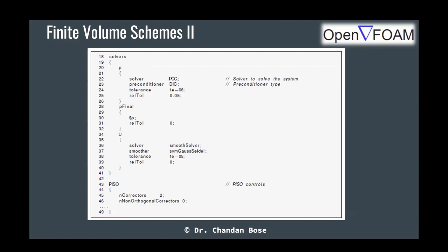There can be two reasons. One is that you have given a wrong name. The second is that you have not activated the OpenFOAM environment. In that case, even if you give the correct name, it will not be able to find it. So you have to source the bashrc file. If you forget to do that, it won't recognize that OpenFOAM is installed in your operating system. Source the user directory etc bashrc. And I told you that you can create an alias or add it to your system bashrc so that whenever you switch on your computer, it automatically activates it.